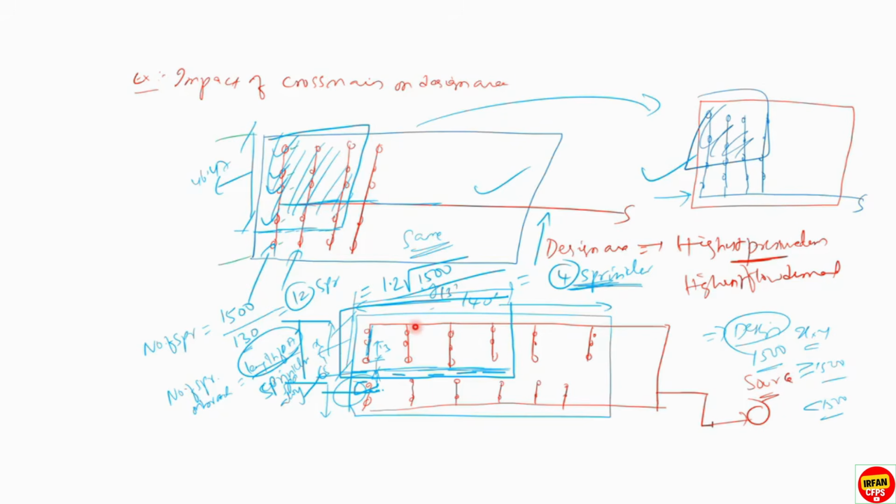Now, the next topic. We discussed the rectangular shapes, right? We'll discuss the L shape and step design area method. Still, we did not move to the non-uniform spacing of the sprinklers. Here we are discussing only if you have uniform spacing of the sprinklers. Now we will discuss non-uniform spacing of sprinklers. If in your project the sprinkler spacing is non-uniform, then how do you select the design area? We will discuss that one.